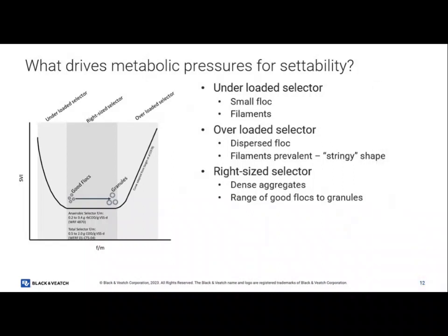So in terms of forming that, what you're controlling in your process is, one, design. I hate to say it, if your reactor is a completely mixed reactor and it's square, you don't get this gradient because it's all the same concentration. So sometimes you're going to be hamstrung at your plants, to a degree, on what floc you can make if you don't have well-sized selectors and aeration basins.